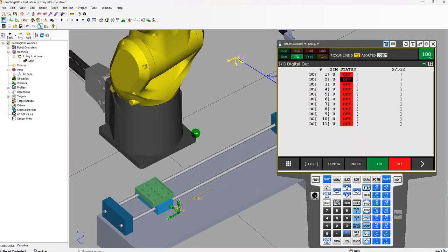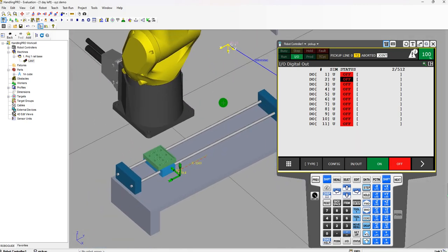What more information if it's an input, I mean, from the robot's perspective, it's an input of this robot, because it should be connected to a device. You cannot really turn it on here. You have to first click this IN/OUT to switch to the digital input list. Then for the input you want to simulate, you need to first set up the simulation status here.